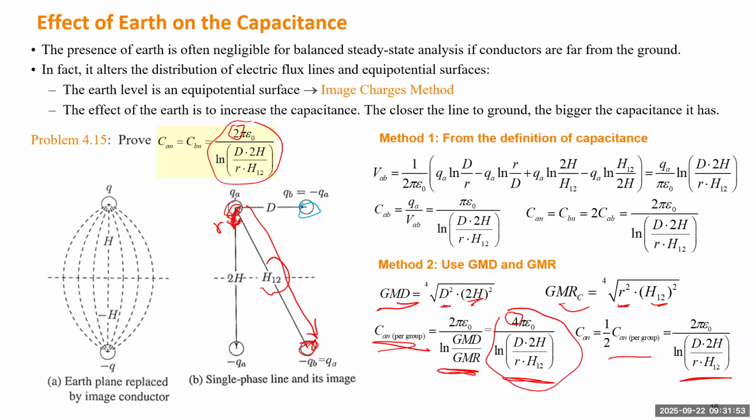So such a restoration plan is very different for a system with all overhead lines. With overhead lines, if you energize a long transmission line, when you increase the load, it may cause a low voltage problem. But for the Long Island system, the overvoltage problem can be the main concern.